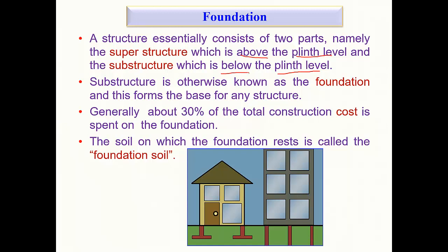The substructure is otherwise known as the foundation, but it is not always the foundation. I will discuss this also. These form the base for any structure. If you look at this figure, these are the substructures of the structure. Why are substructures not always the foundation? Because sometimes you might have a 2 to 3 story building extension below the ground, and at that time you may not consider it a foundation. But if it is a member only for foundation purposes, then we call it a foundation.